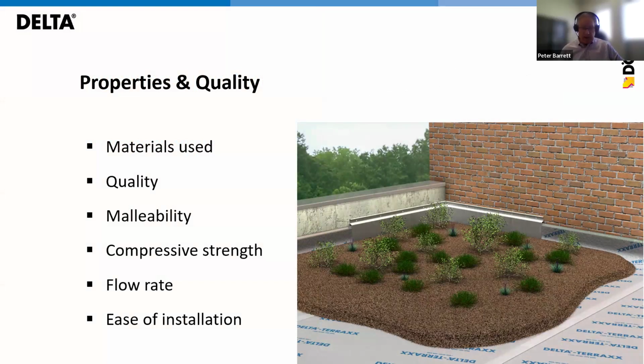Designers will commonly select drain boards assuming 100% of the claimed flow rate on the technical data sheets, but under real world conditions achieve only between 22 and 80% of the claimed flow rate. This gap between the assumed and the in-service flow rate can result in undersized drainage systems that are already less than increasingly extreme precipitation events require.